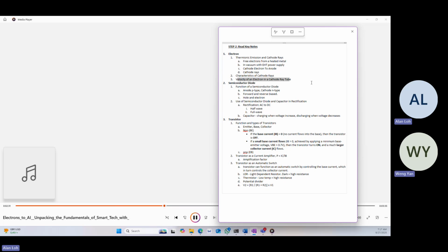current, like directing traffic? Ah, now you're talking diodes, semiconductor diodes. They are the one-way streets for electric current. How? It comes down to something called a PN junction, which is where two types of semiconductor material meet. Think of it like a very strict bouncer. If you apply voltage the right way, we call that forward biased, the bouncer lets the current through easily. Low resistance. Any other way? Reverse biased. Try to send current the wrong way and the bouncer slams the door shut. Very high resistance, basically no current flows. Right, a one-way gate.